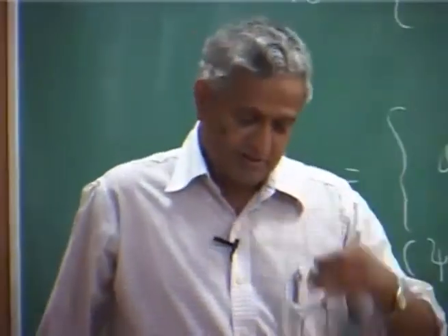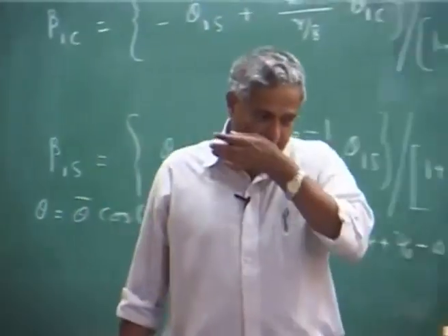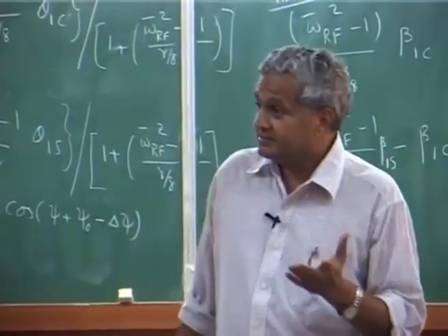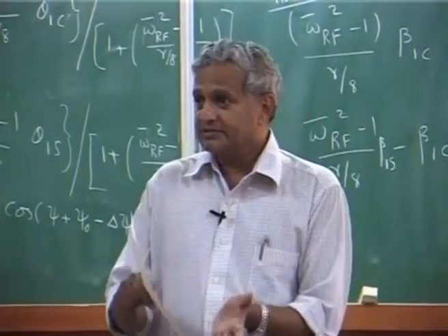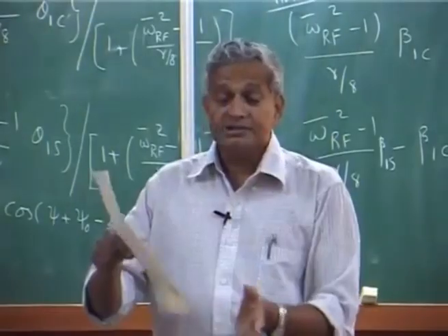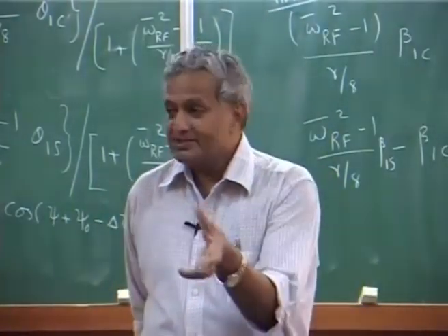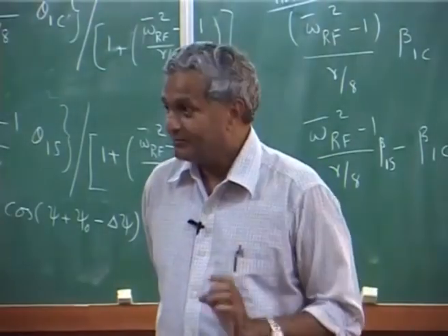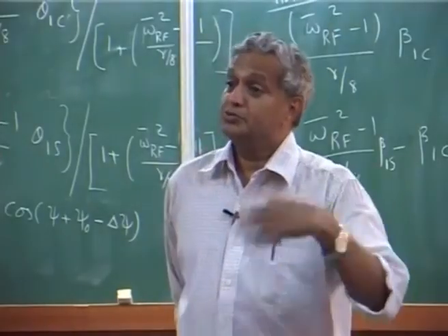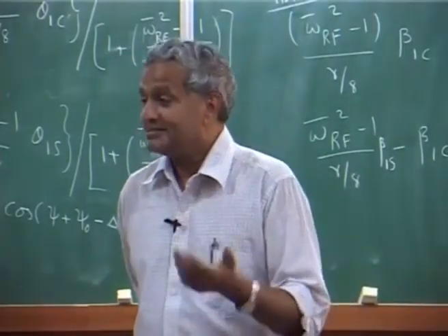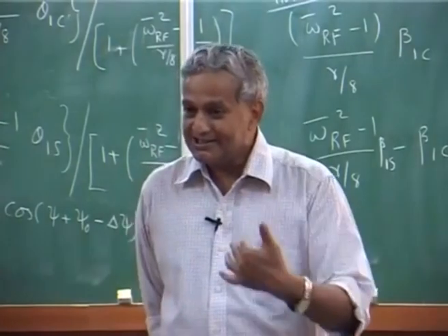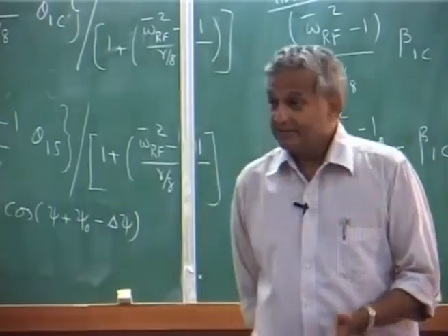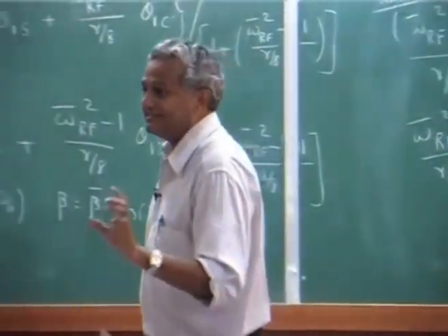And particularly when we, I hope there will be some time for analyzing the flight dynamics, the inertia of the vehicle is different in pitch direction and roll direction. Pitch it is larger, roll it is less. Now, if the inertia is less, what will happen is, if pilot gives an input for pitching down, actually he will roll much more than what he intends to do in pitch itself. That is because of the less inertia in the roll direction. Now, this coupling is very difficult for the pilot to fly.